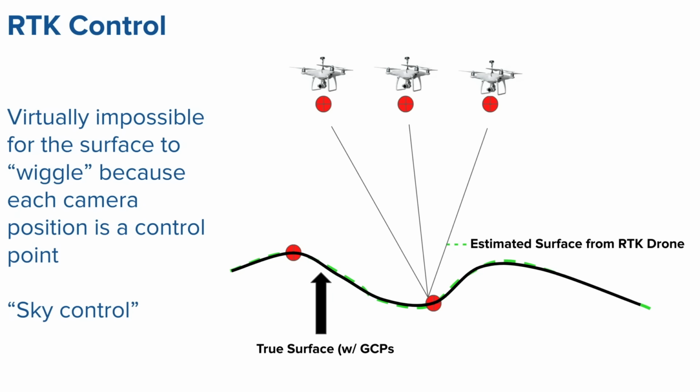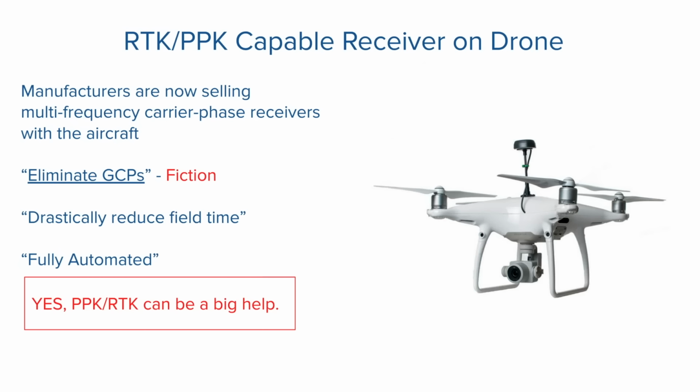But what you can see, and this comes up a lot in user forums, and people are encountering it more and more as they invest in RTK drones, is that if you abandon GCPs, while your horizontal accuracy is good, you end up with a vertical bias, a simple vertical offset in the data set you process. We're going to show you a couple examples.